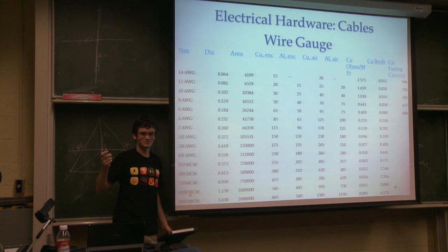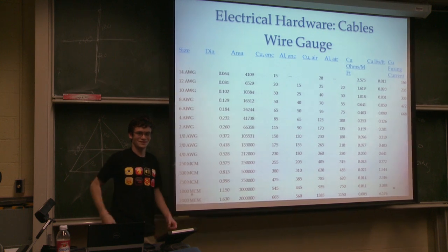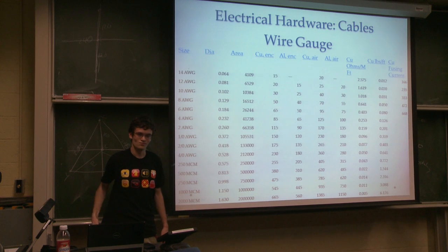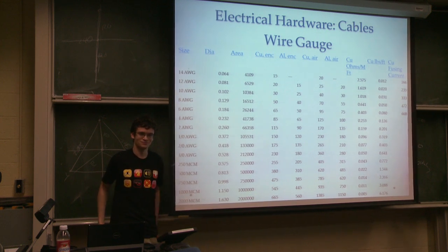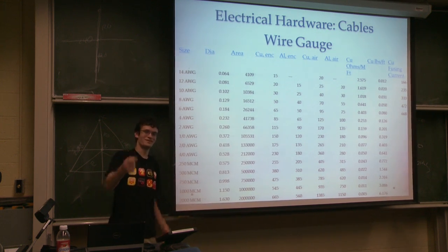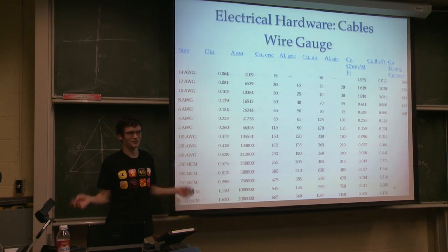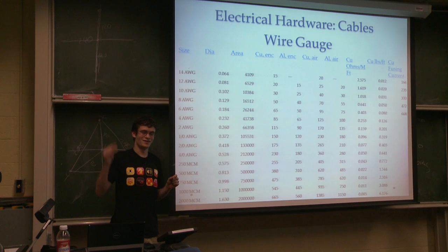They draw more current when they have a lower voltage. So, really long cable run, really thin cable, and heavy load at the end, and all of them were in use.